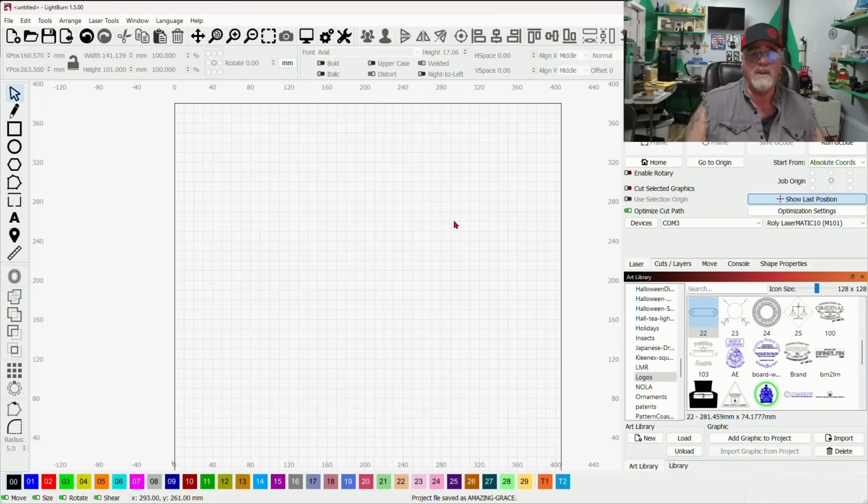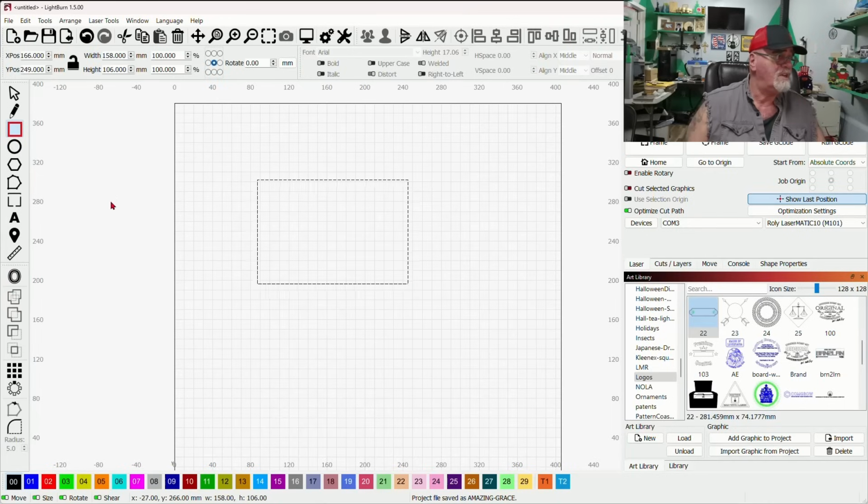And speaking of the laser tools, something else that has been added in version 1.5, let's just draw out a rectangle here, and let's set this to a width of, let's just say, 20 by 10. You'll see what I'm going to do here in a moment. I'm going to snap this to here, and then I'm just going to duplicate that, and move it over to here and duplicate that and move this one over to here. I'm not going to align these or anything else. And basically what I'm going to do here is weld these real quick so that we have tabs.